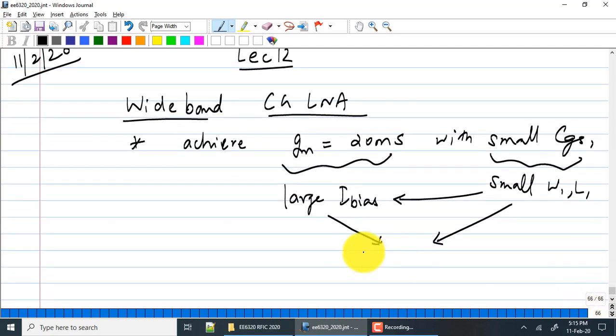Put these two together. Your current density is extremely low. Taking a very small device, pumping a lot of current. Okay. VD-SAT, VGS are both going to be extremely large. You're making VD-SAT larger and larger by making the device smaller and smaller and increasing the current.